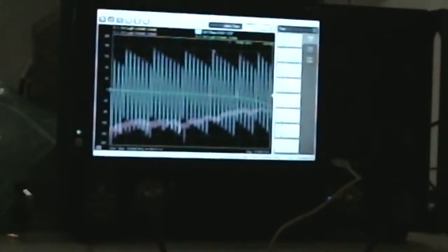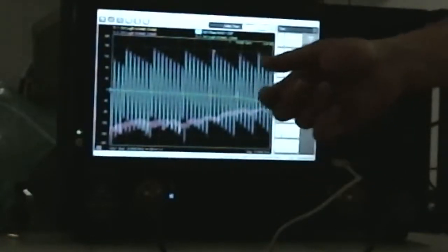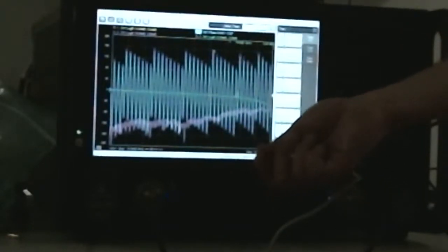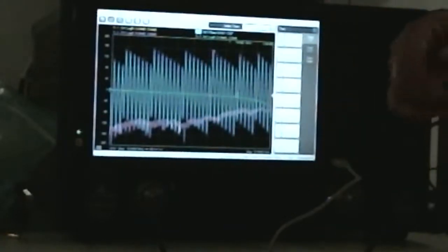BNC is way worse. That's just something I'll tell you up front. I've tried to show this to a customer with BNC, because they said, oh, I'm just going to build some BNC antennas. We used SMA to BNC adapters on the front of the network analyzer, and then we connected a BNC cable. We just bent the cable like this, and then we went back to the antenna, and it didn't even go back to the same place because the cable varied so much. There are some people who make a mechanical BNC calibration standard, but I would never tell anybody to ever use BNC for impedance matching.